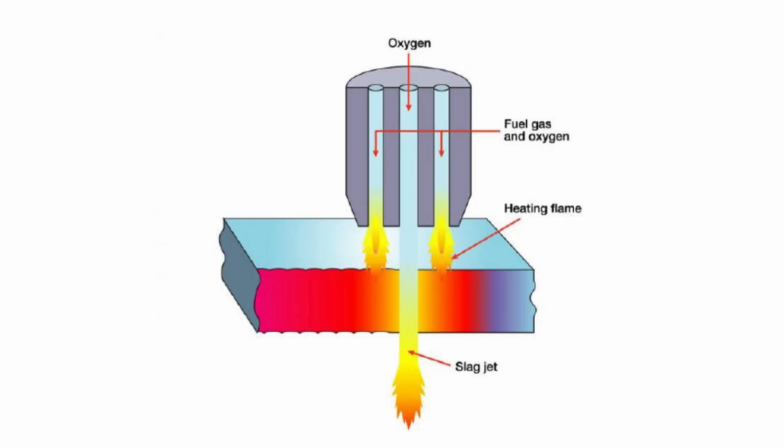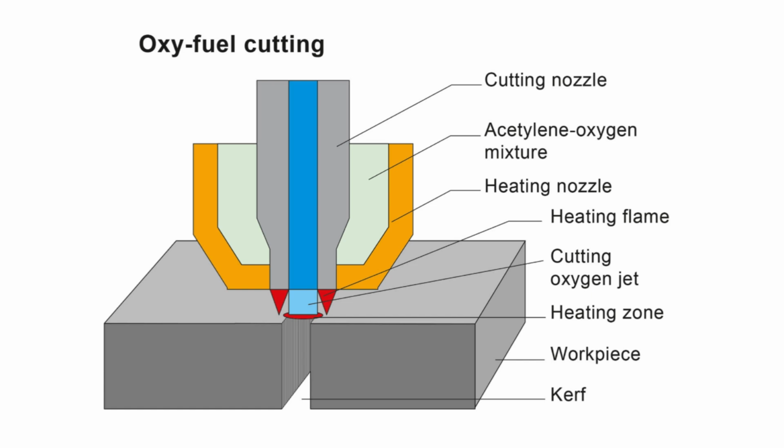The flame cut process functions on the principle that a jet of pure oxygen is directed at a surface that has been preheated to its ignition temperature. The ignition temperature is the point at which the metal will ignite in pure oxygen. The material in the path of the jet is oxidized and ejected, resulting in a cut. The process does not function on all metals.